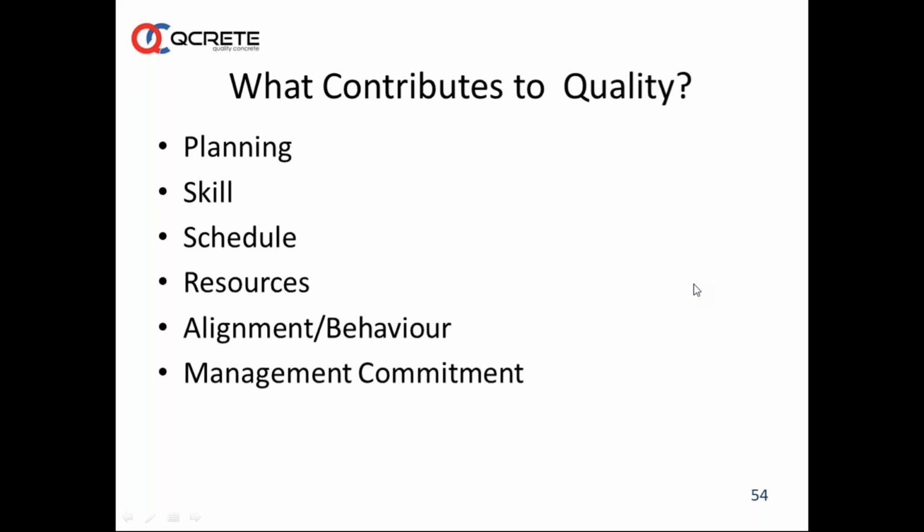Mr. Srinivas Babu, whenever we are using higher grades of concrete, like say M50 and above, especially in conjunction with PC based admixture, whenever we are doing concretes with a higher dosage with lower water cement ratios, especially the PC admixtures give this sticky concrete actually. So one of the things that you can do to reduce the stickiness, the simplest method, is to reduce the cementitious content if possible.